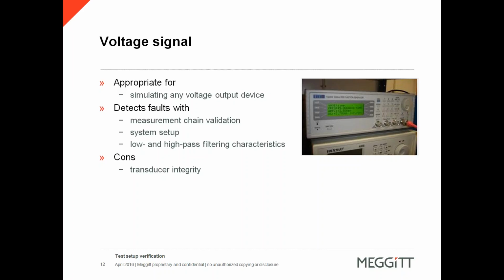It could be as simple as connecting a battery to the input leads of the cable, or by using a more complicated and thorough test method with the use of a function generator or handheld signal source. Such a function generator or handheld signal source allows for the use of a calibrated signal that can be varied in both amplitude and in frequency. This would result in a more thorough method that can be used, for example, to verify the amplifier gain scaling settings and also the filter roll-off values for each channel.